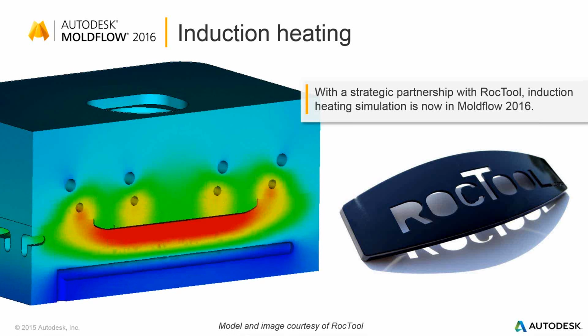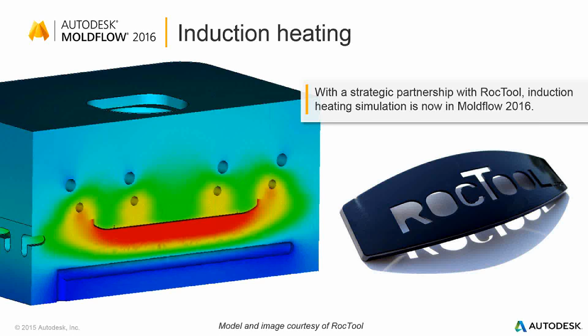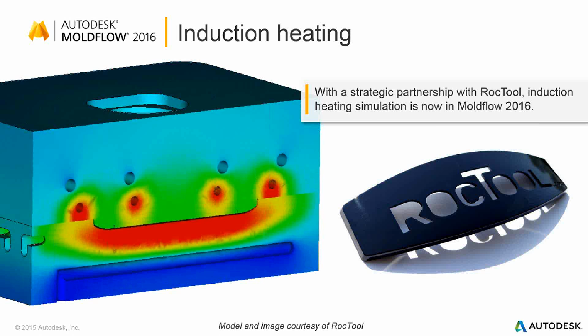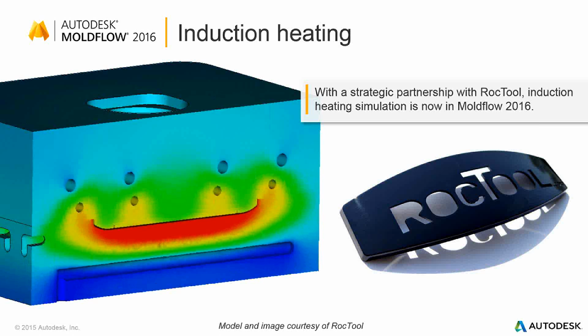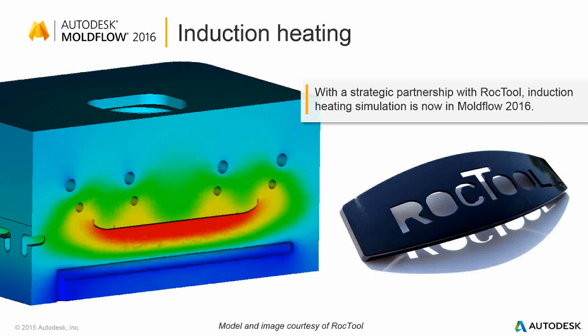Now, the heating happens very quickly. Just in a fraction of a second, that tool will be heated up in the location close to the mold surface temperature. But it's a very local effect, which means you don't actually have to cool the entire mold down, which is something you would get with more traditional rapid heating and cooling technologies that are out there.